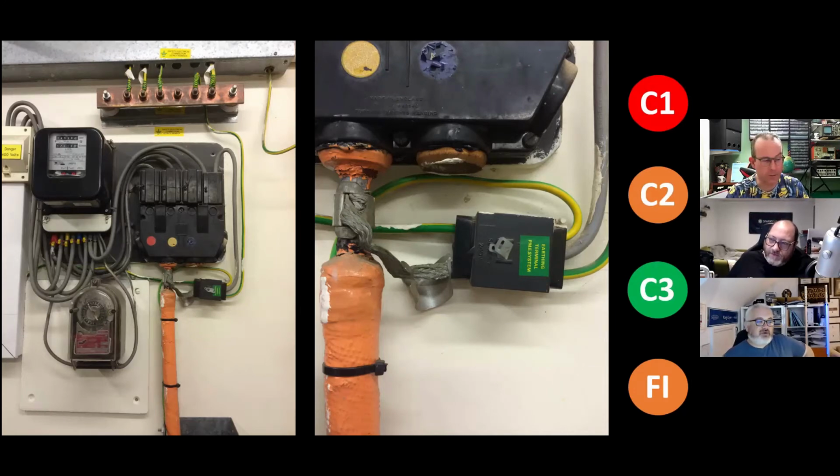I think kind of the point of this being, though, as well, is it's not what we were taught. When I was taught, it was TNS, TNCS, or TT. Yeah. The earth rod's every 30 meters. No, it bloody well is not every 30 meters. Even at the joints, they just put a coil of copper wire, put the joint on top of it, and that's it. And even there, they're not even driving the electrodes like they're supposed to be doing under their own standards. So it's not as great and as good as we all think it is.